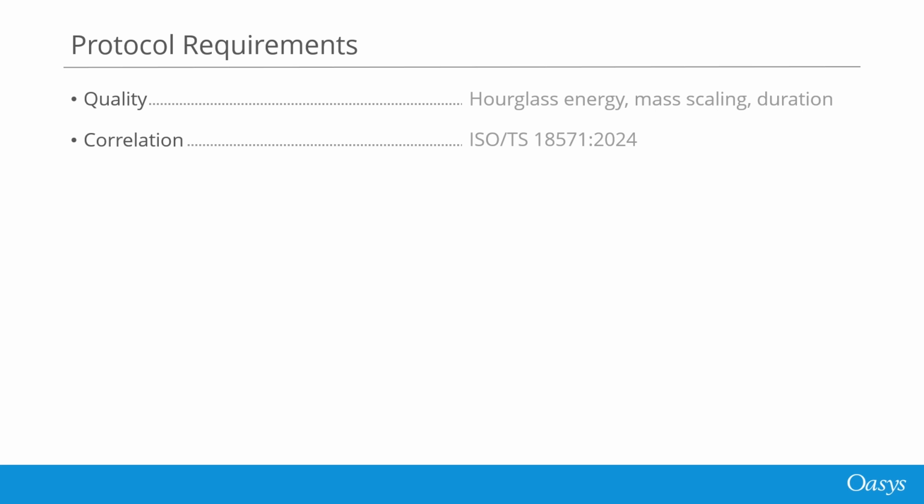Injury assessment. In virtual testing protocol, injury assessment criteria are compared between simulation and physical data as part of the validation requirement, with Euro NCAP's validation criteria 2 and C-NCAP's correction factor A. In the Euro NCAP protocol, validation criteria 2 impose an acceptability limit on the difference between the ratios of the injury metrics and their limits when compared between simulation and physical test.